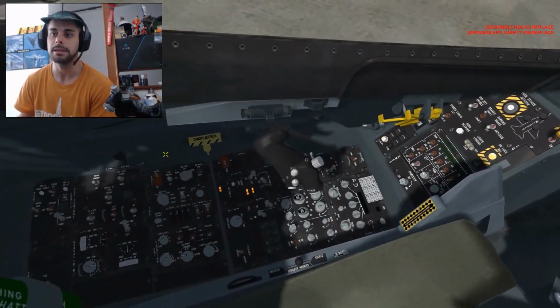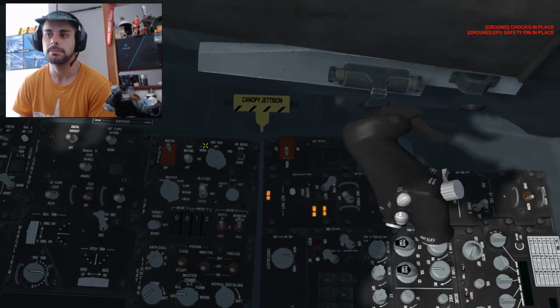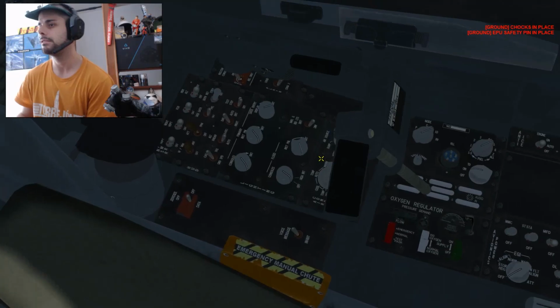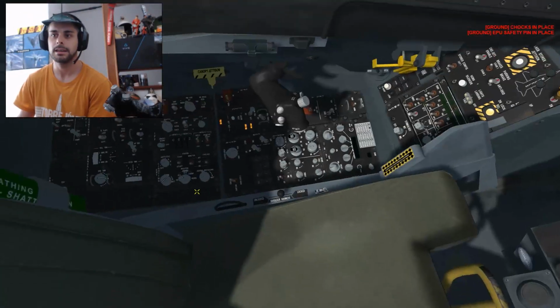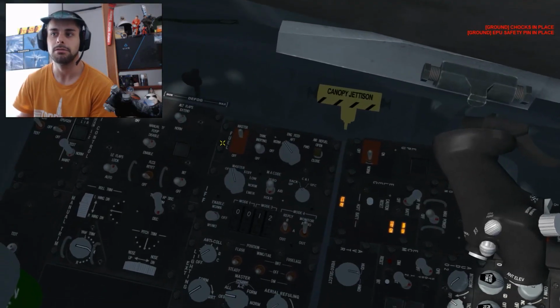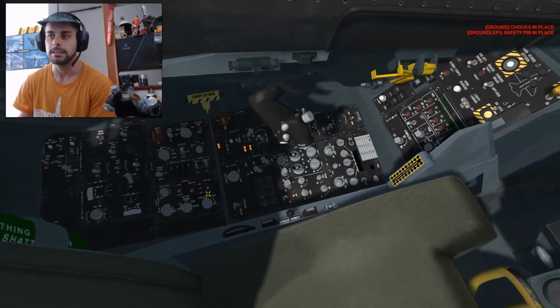Now to start up the engine, I'm going to turn engine feed to norm. There. Also, the air source in norm position, and check that the master fuel is good in the up position. Okay, that's all.